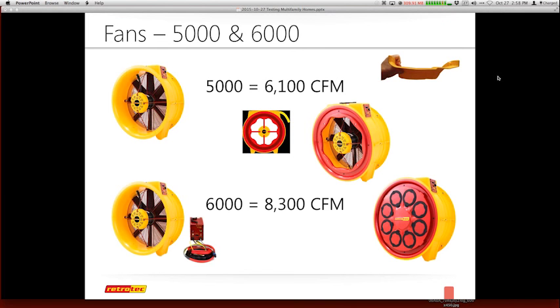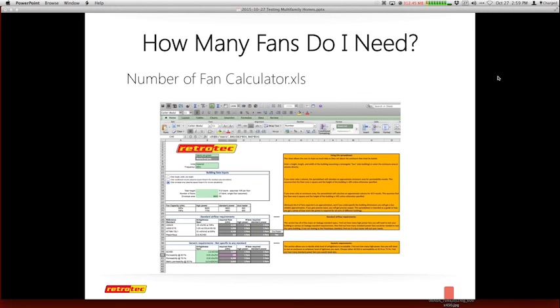It makes it universal because these plugs or openings also work with the duct testers. So you can go down to a smaller single opening and test around, say, 5 to 10 CFM of a unit with a blower door. That's for the incredibly tight situations you may have in some of the homes that are achieving these remarkable numbers.